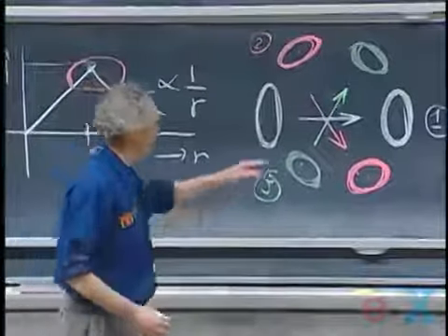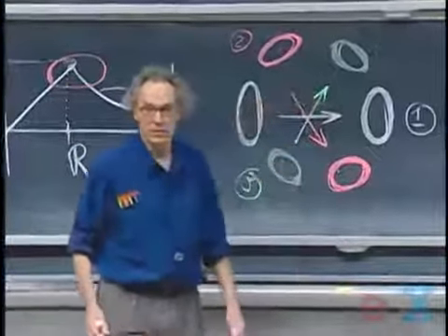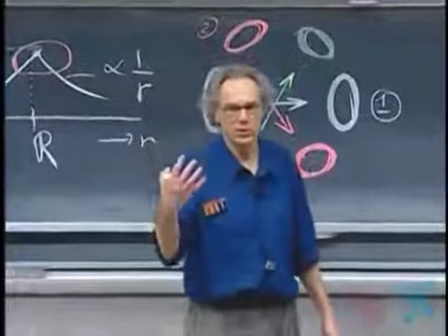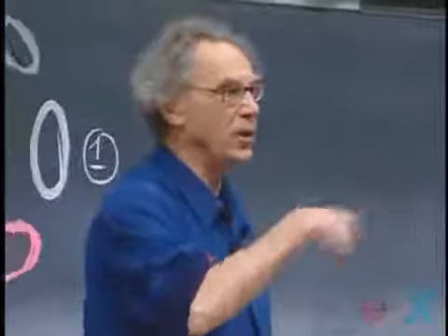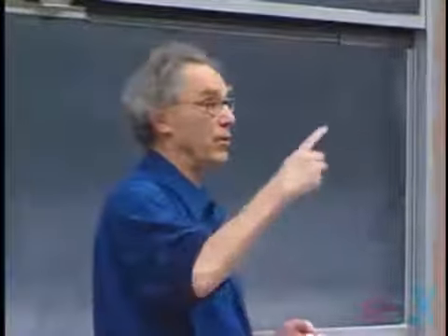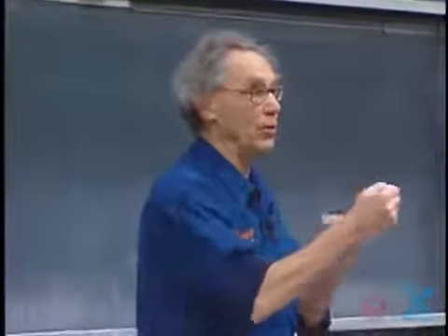And when the magnetic field rotates around, there is a continuous magnetic flux change to the surface of that conducting sphere or egg, and so it's going to run eddy currents. Now if you have an eddy current going around and you have a magnetic field, then the magnetic field and the eddy current will cause a torque on the current.